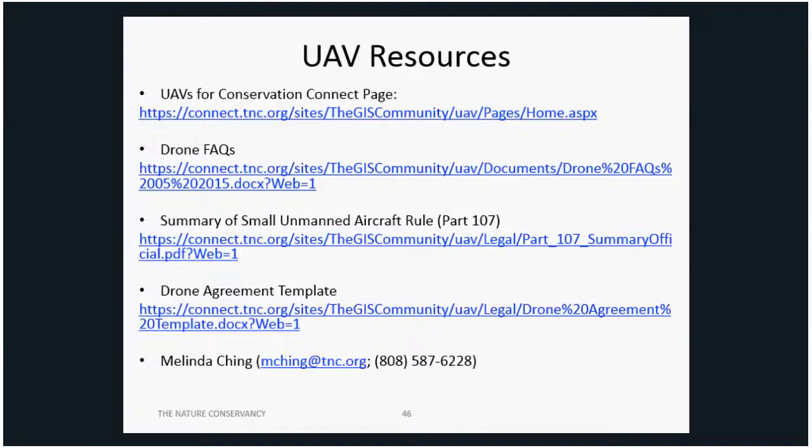Yeah, that's a really good question. I support the Asia Pacific region, and I've done a quick survey, and you're right. There's no real limitation placed on that. We want to adopt a strategy whereby the operations we have in non-U.S. countries are similar to the operational guidelines we have in country: staying away from the airports, observing power lines, keeping line of sight, flying under 400 feet. Those kinds of things we want to remain consistent. So initially, that's going to be our stance.